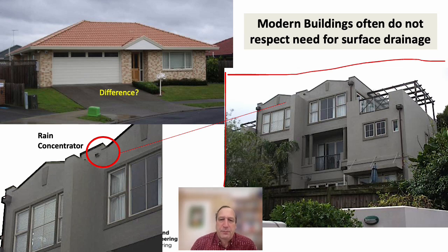But there are also some pretty interesting details. You'll see there is a pitched roof hiding in the backdrop there. That's pitched, and the water is running internally into a gutter, and then it has to come out. If you look here on the drawing on the left, it has to come out of what's called a scupper, but that scupper dumps its water directly onto this unheated wall system.